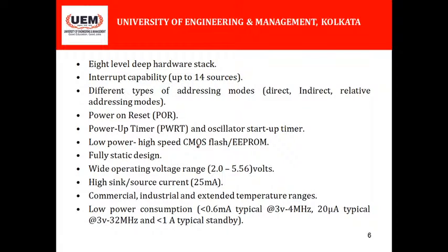Power on reset feature is applicable. That means whenever we power off the microcontroller, all the data stored in the data memory, especially in RAM, will be lost, and similarly all the register arrays will be emptied. Whenever we power on, it will start once again and continue to load the data once again.